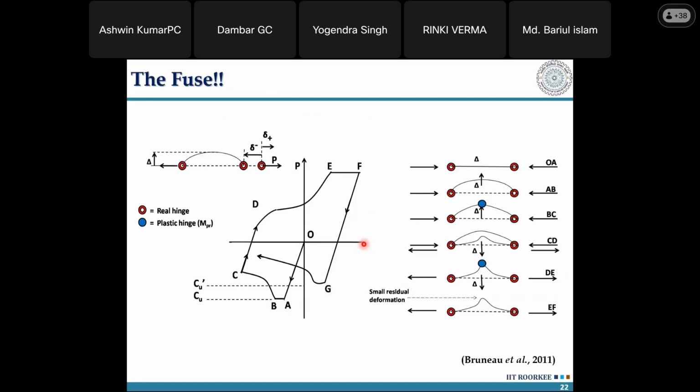Buckling strength, A.K. Jain sir found 55% in most experiments, but if you look at the literature, Dr. Narayan, you will find that 55 is a very high value. You have to understand that, let's say our drift under MC level is 5%. Calculate in that way: for 5%, what would be the maximum axial deformation in the brace? If you do n number of cycles, yes, the braces come under an ultra low cycle fatigue case, where under an earthquake only 20 or 30 cycles are what the brace is going to undergo. In that number of cycles, how much is the drop of compressive strength? You look at the literature, and I have experiment results also with me. So you will find that whatever they said is true.